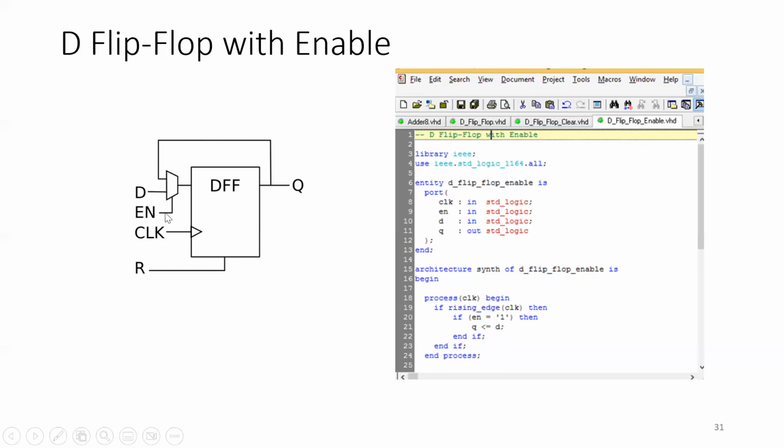I believe you would get Q because... Excellent. Because this is 0, this is 1. This is line 0 and this is line 1. If enable is 0, I will get Q. That means no change in output. The output, whatever it is, no change, remain as is.